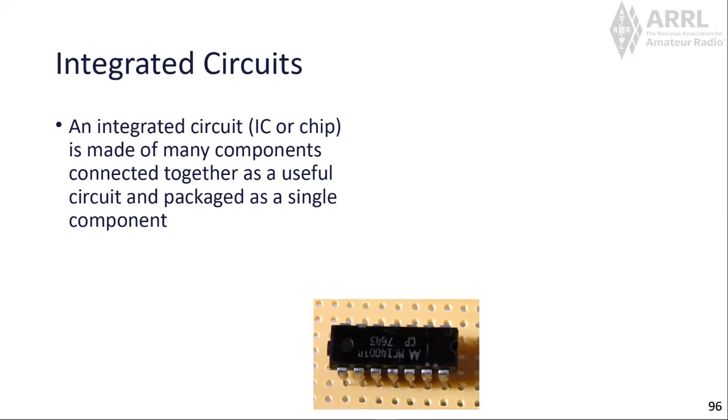In this case, we have an IC down here. It's a 14-pin IC. Its type is a 7643. They got the number upside down, but you can still read it. It's made by Motorola. I can tell you that from the... you know what? That's a type 1400. I can't tell. That's the 60, that's the type. 7645 would be the production date. So it was made in the 45th week of 1976.